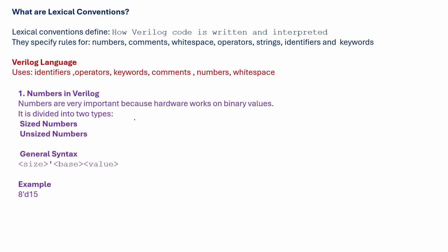I just want to drive my hardware and check whether it works or not. I want to pass some stimulus through numbers only. Some x equal to 4 tick binary 1010 I'm giving. This is my number I'm passing.